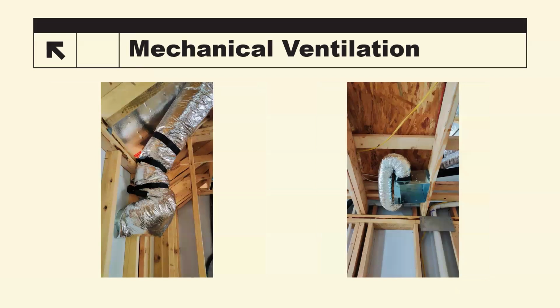And then, of course, as code states, if mechanical ventilation is part of the duct system, if it's tied into the air handler, it must be duct tested. It's not excluded from being tested. These cannot be taped. They cannot be closed. They need to be left as they're going to function. If it has a mechanical damper that opens and closes when not in use, that damper should be closed. But if it has a damper that actually has to be operated manually, you shouldn't get up in the attic and close that. If it's going to be left open at all times, you need to test it as it is.